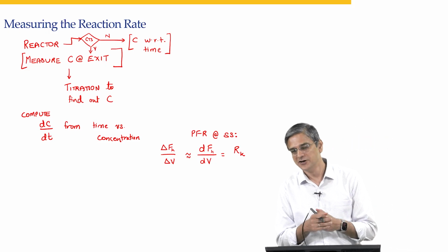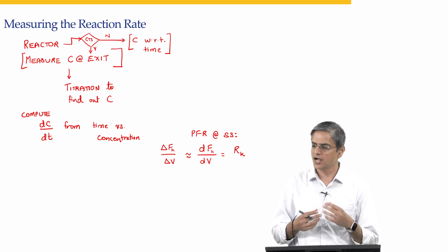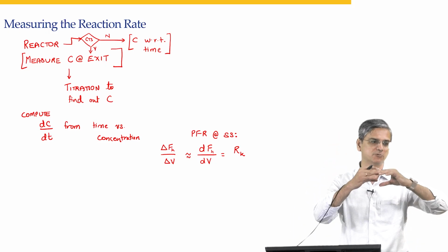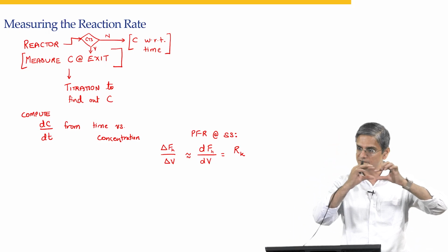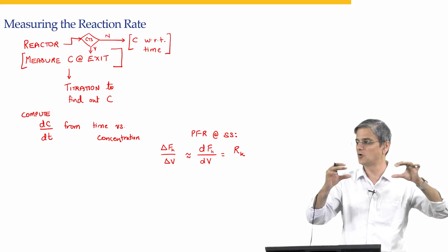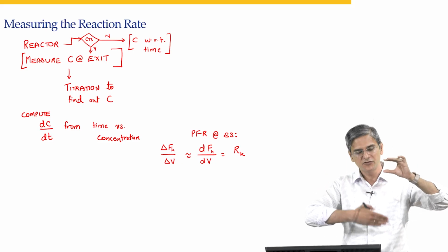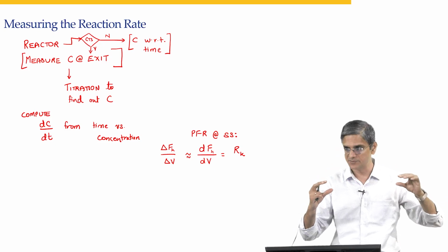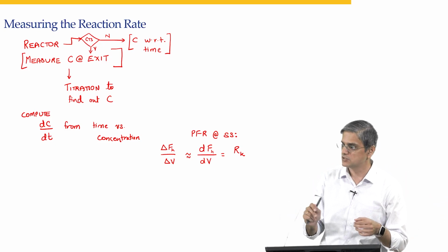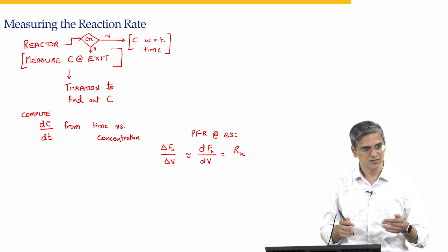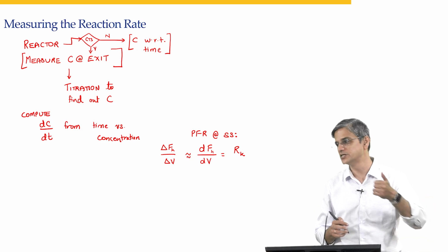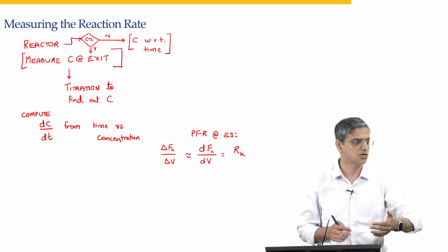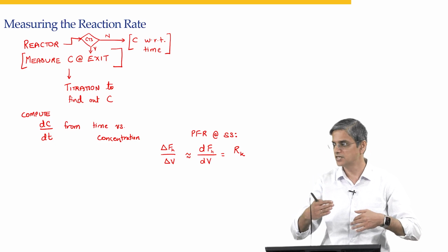So, what would happen under different conditions is that the flame will propagate to a particular point and then get stabilized at a particular point, and that flame is fairly small. And if you consider what the actual flow rate is versus how small the flame is, keep in mind you have started with a flow rate of 5 liters per minute, and the temperature has gone from 300 to say 2000 Kelvins, or maybe 2100 Kelvins at the flame.